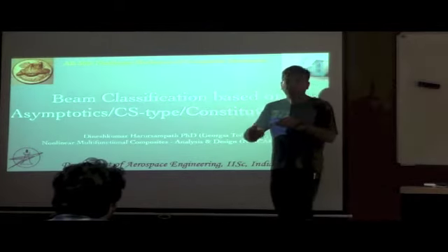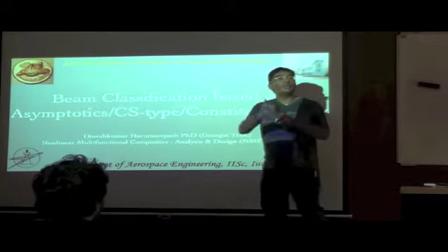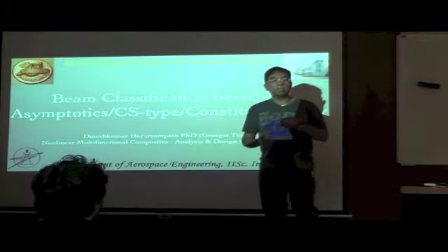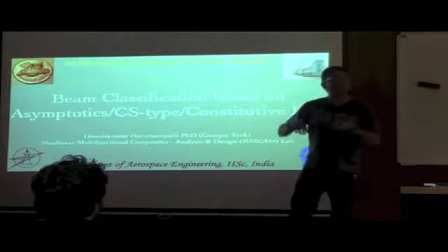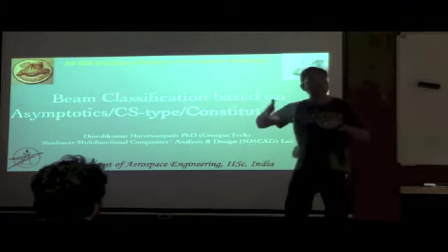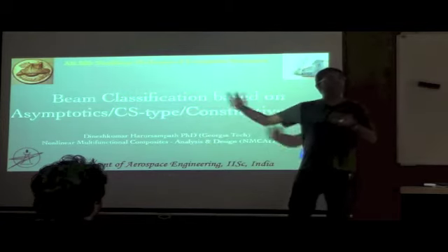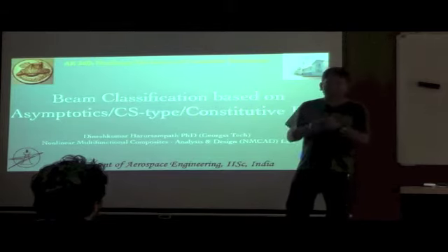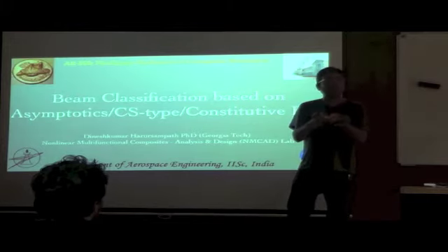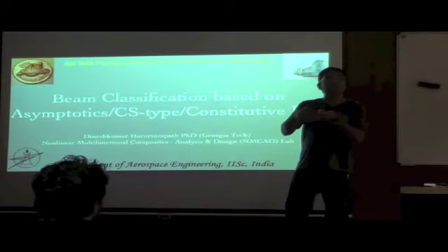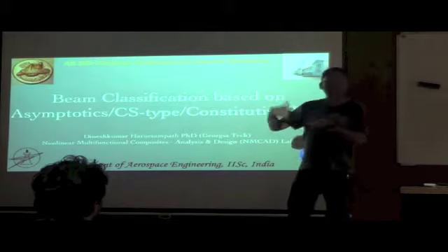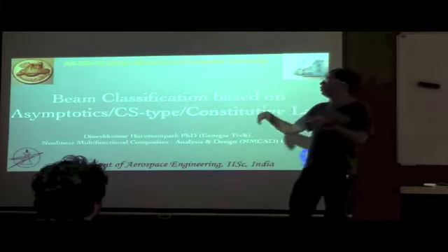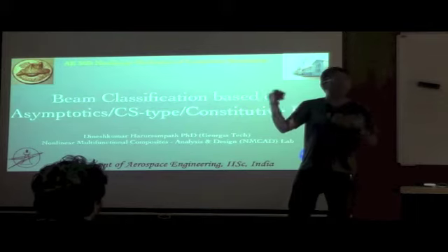In other words, all the dimensions that you take within the cross section for a square cross section or a solid circular cross section for that matter are the same. So therefore there is no small parameter associated with it, and the kind of asymptotic theory that will result will be unique to that class of beams. On the other hand, when you do it for a strip-like beam like this, you have not only the regular cross-sectional dimension divided by length small parameter, but you also now have within the cross-section itself another small parameter, which is the thickness divided by the width, and that will result in a different set of asymptotic theories, and therefore you know that those theories are applicable for this kind of beams, the strip-like beams.